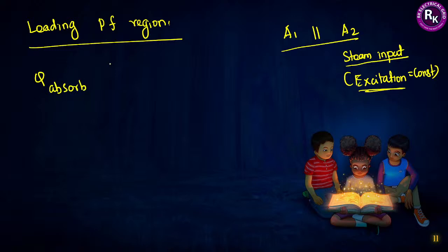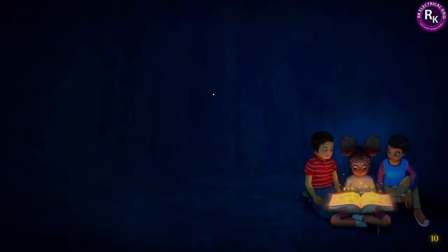Now let me conclude everything. The reactive power absorbed by the alternator in the leading power factor region will be directly proportional to the load of the machine, or I can say it will be directly proportional to the steam input. Don't get confused between the previous statement and the present statement that I am giving now. Previously I told you there are no changes in the reactive power. Leave that statement.